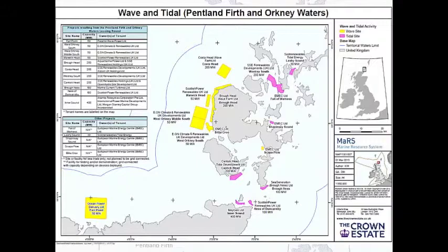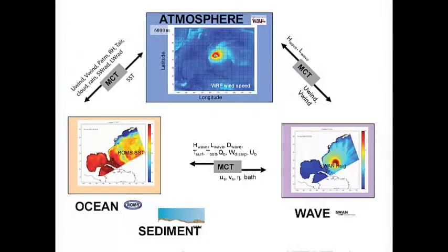Again, I've been using this ROMS model, and it's part of a larger package that we implement called COAST. The whole system is coupled through this model coupling toolkit, MCT, an acronym that's familiar to some people for other purposes. So we do fully couple these and implement the sediment transport model. But today I'm just going to be focusing on the ROMS model. The WRF, by the way, is the atmospheric model. It's a sort of downscaling atmospheric model to get very high resolution wind input when topographic effects and other processes are important.